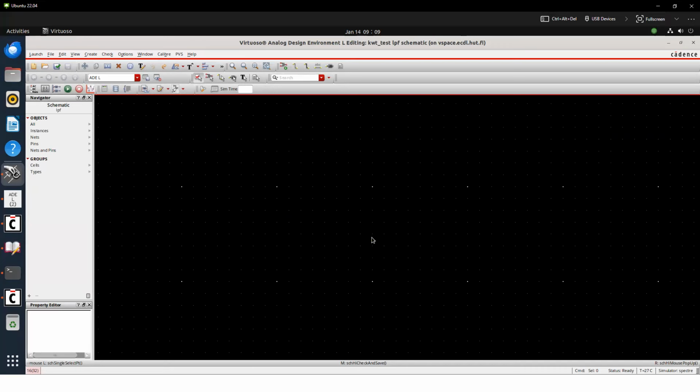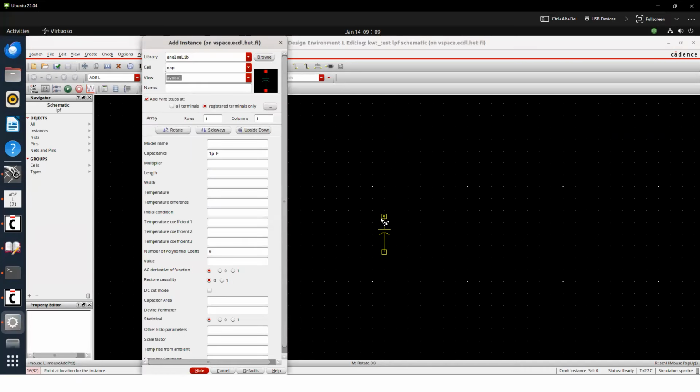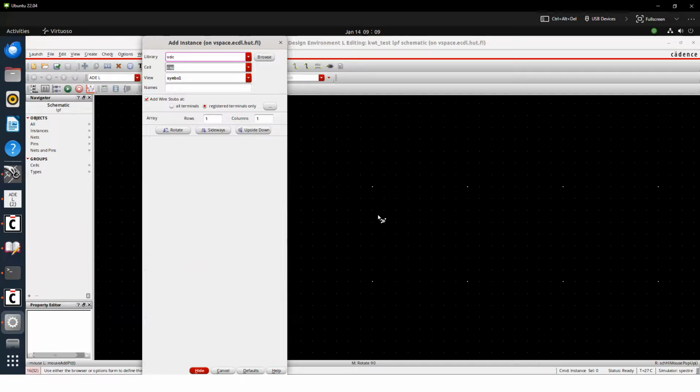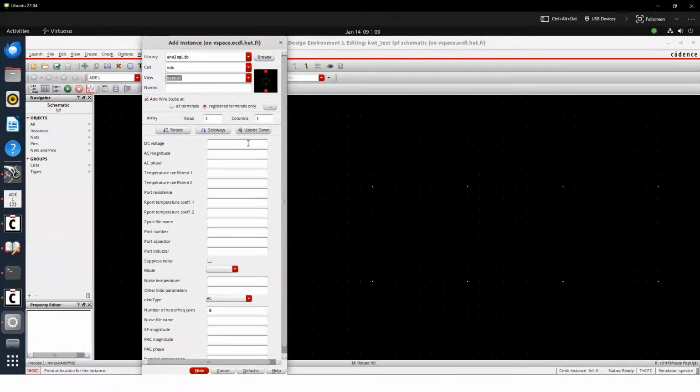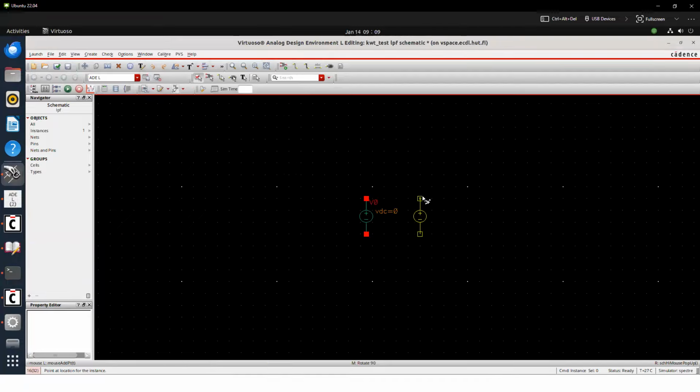Anyway, so you will do this kind of CAD exercise through this course. So first, I would like to go through is we can set VDC here. No, sorry. Analog lib, VDC. Then we have DC voltage equal to 0. This is DC, right?